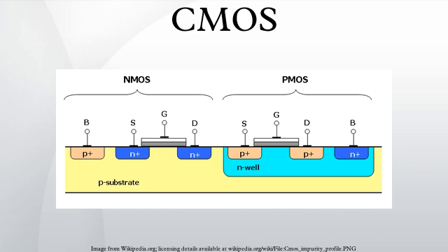The image on the right shows what happens when an input is connected to both a PMOS transistor and an NMOS transistor. When the voltage of input A is low, the NMOS transistor's channel is in a high resistance state. This limits the current that can flow from Q to ground. The PMOS transistor's channel is in a low resistance state and much more current can flow from the supply to the output. Because the resistance between the supply voltage and Q is low, the voltage drop between the supply voltage and Q due to a current drawn from Q is small. The output therefore registers a high voltage.